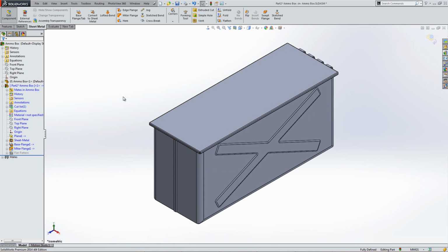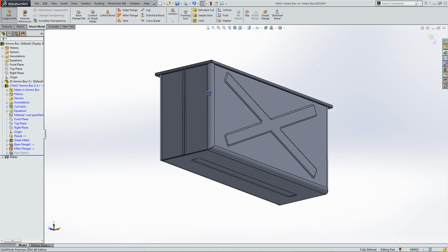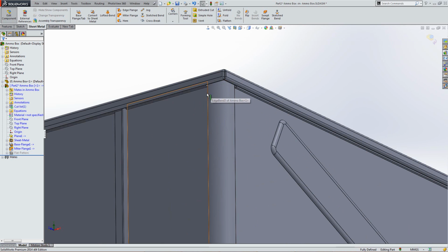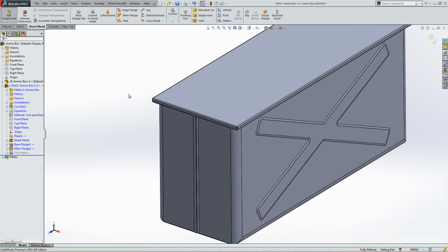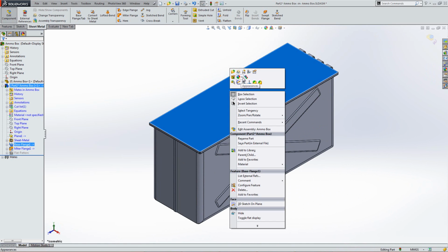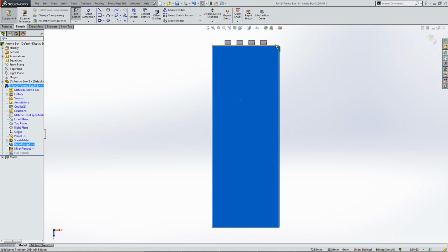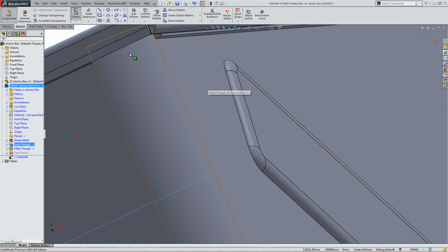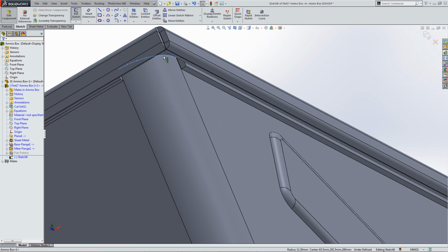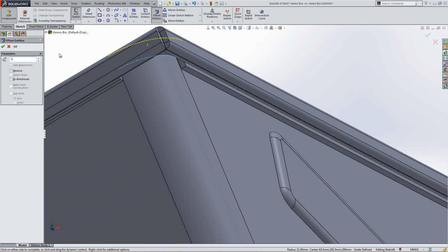Alright, so now I want to actually cut away these corners, just to match it so they're rounded corners like this. Now this is not exactly a good looking model, I know, but it's just giving you an example of what we could do. So actually I'm going to convert this edge, or offset it anyway. Offset it by 1.5.